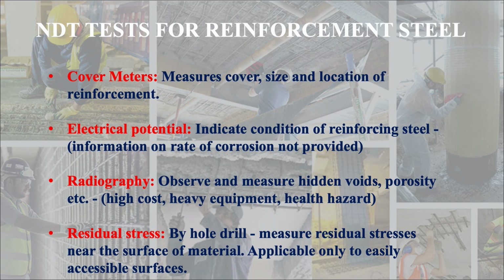Then the residual stress test can be done by hole drilling. It measures residual stresses near the surface of the material. It is applicable only to easily accessible surfaces.